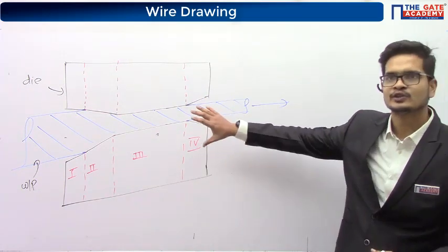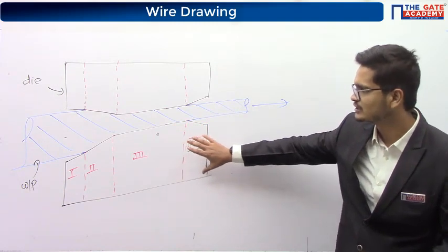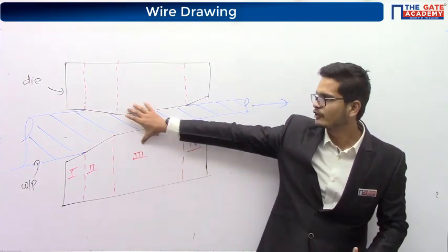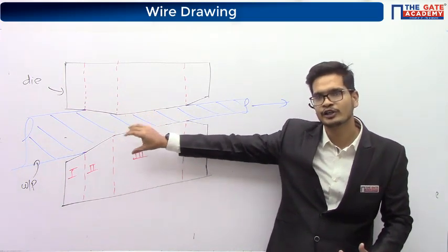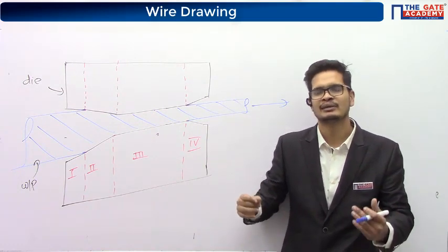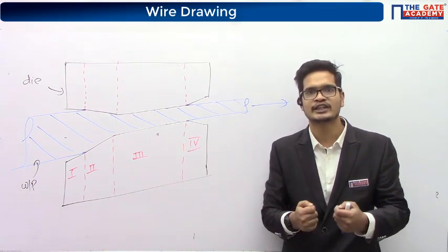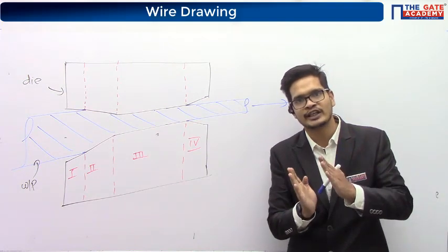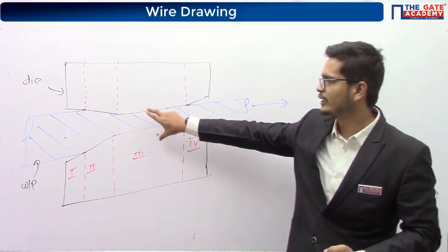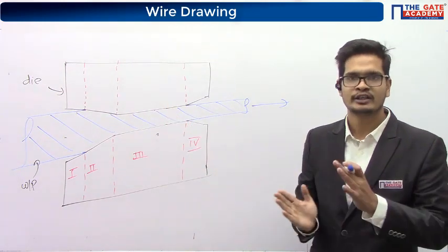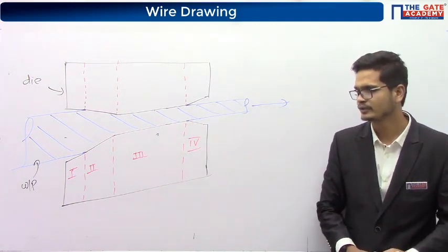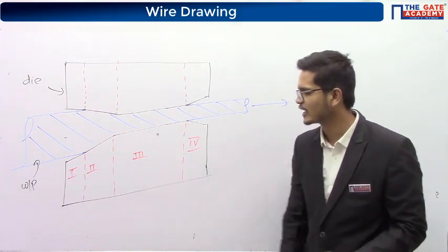Okay, so this is what is happening. Obviously, to get whatever desired size you want, you can cause more deformation so that it will come back to its original size, right? But for that you will have to do precise calculations, like how much you have to decrease so that after recovery it becomes the size that you want. Here, by retaining the load for some time, you get the desired shape, and it is okay, right? So zone 3 is called the sizing zone.